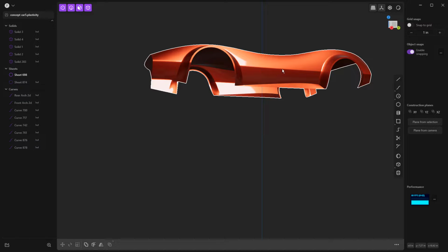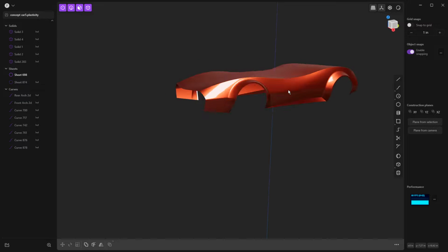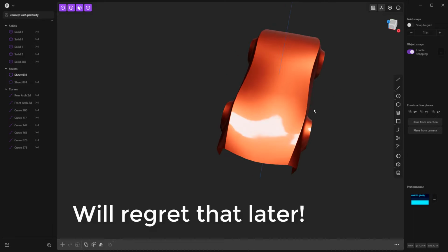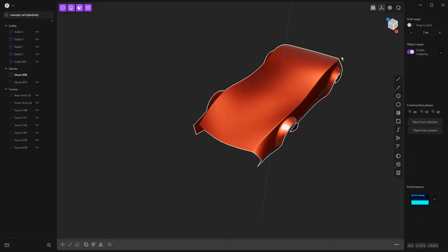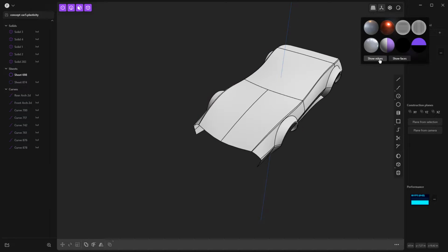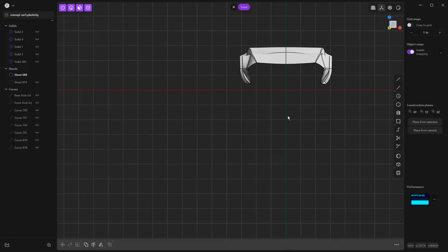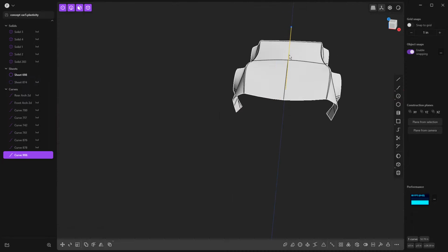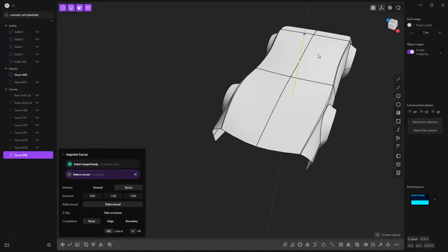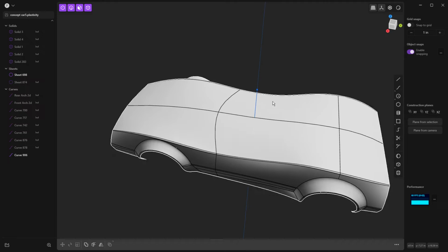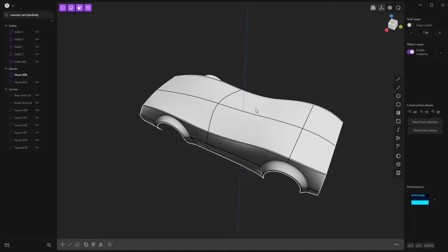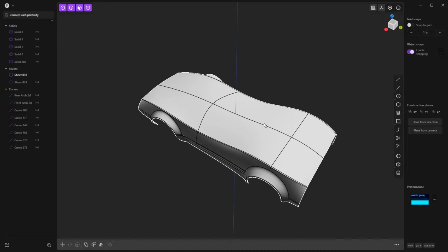All right. So I really like the hard body line there. I'm thinking that I want one down the middle. So I think to end this video, let's go ahead and make a hard body line down the middle. And the way that I'm going to do that, first, from the front, I'm going to make a line from the origin just straight up and down. And then we'll do Shift I, which will essentially just let me split the rest of the body. It's still all one piece, but now it has that seam down the middle.